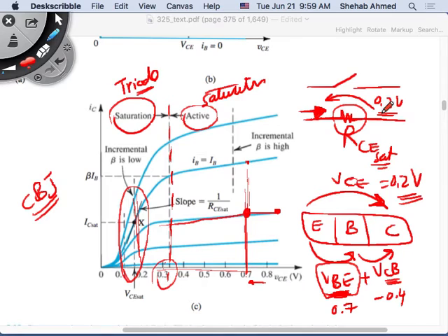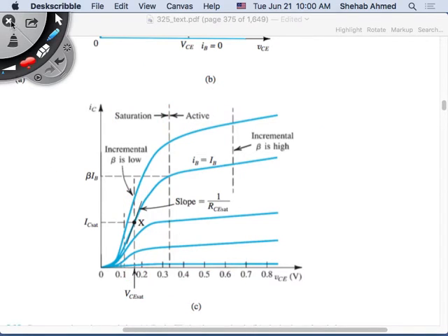That's not very interesting. In the MOSFET application, you will see that in triode operation mode, the value of resistance is very small, much smaller than the BJT. The slope is even higher. So in this case, operating with a MOSFET as a low voltage switch may be very interesting. Operating a BJT as a high voltage switch may be very interesting, right? So this has applications and this has applications.